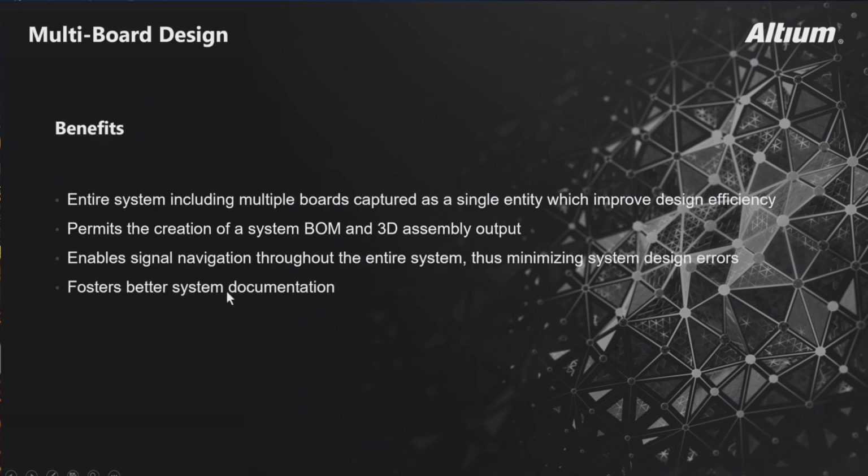So for multi-board, the real benefit here is that you can collect together multiple projects that were designed at a lower level, and then have one top-level project from which you can generate documents, primarily bill of materials and other common information, and then you can do the 3D assembly. So there's two parts to it. There's the schematic representation, which is pretty neat, and there are a lot of benefits to doing that.